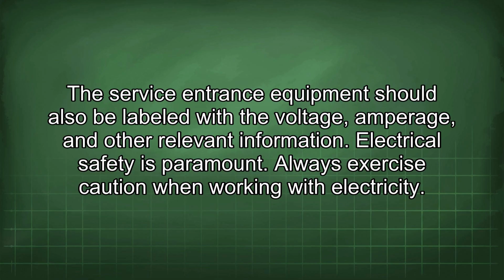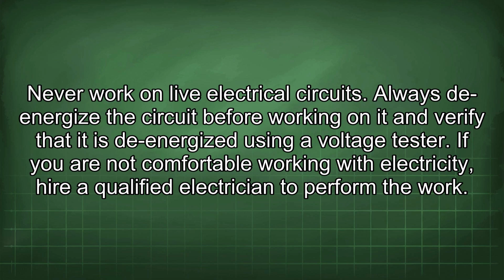Electrical safety is paramount. Always exercise caution when working with electricity. Never work on live electrical circuits. Always de-energize the circuit before working on it and verify that it is de-energized using a voltage tester. If you are not comfortable working with electricity, hire a qualified electrician to perform the work.